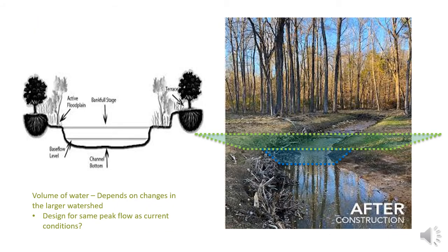This slide shows why it's so challenging to do stream restoration, because we're not actually talking about a static level of water. Obviously, flow changes over time, right? We have seasonal impacts, but realistically, we have to design for normal conditions. We have to design for drought conditions, when water flows are very small, and we have to consider the impacts of flood conditions.